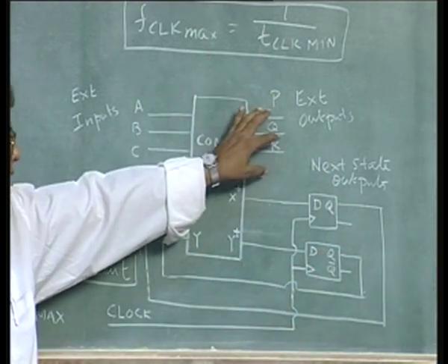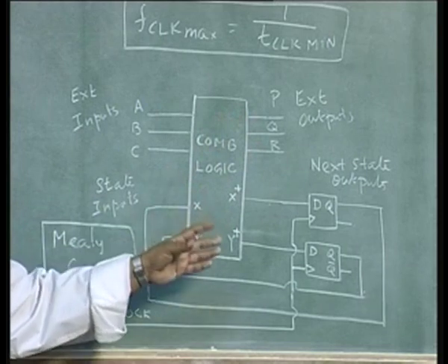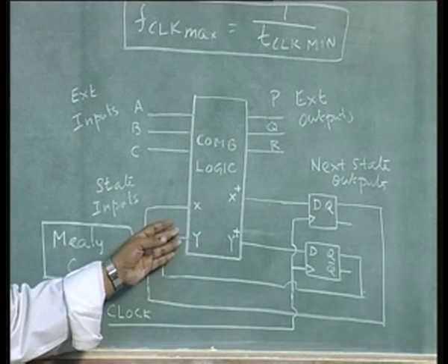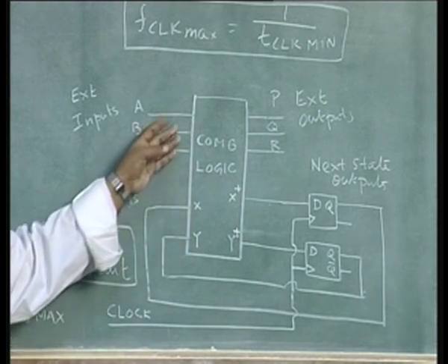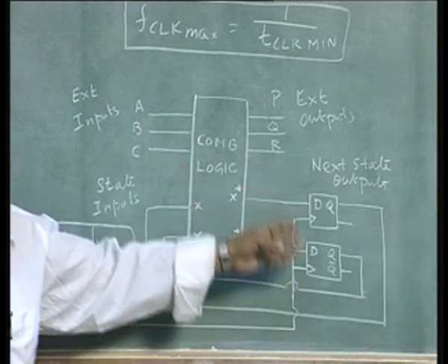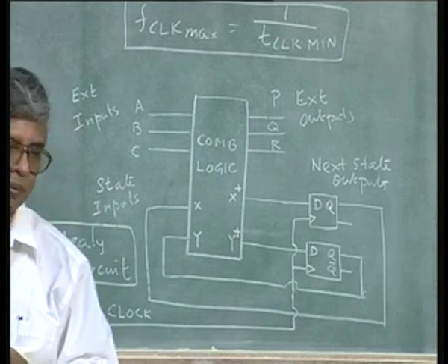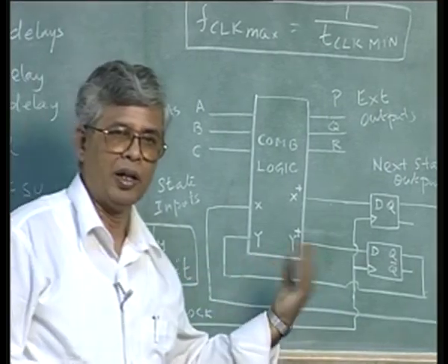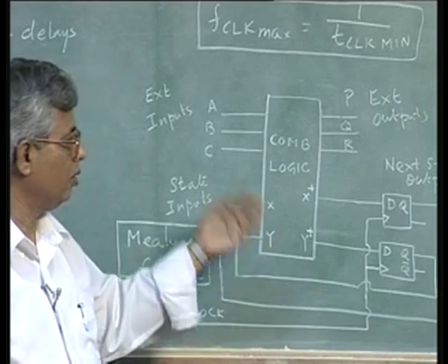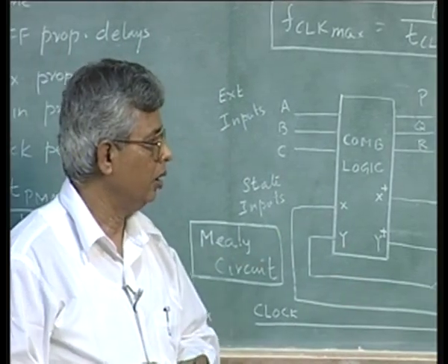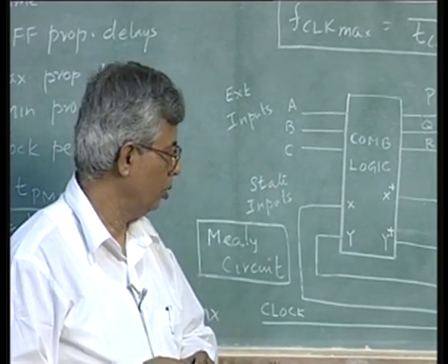What are the outputs required externally? What are the states? How many states are required? Based on that, state variables are defined, and the present state variables along with the inputs design the next state variables, etc. This is a standard procedure that gives a lot of design methodology, which we will adopt in the subsequent lectures in order to design different types of digital systems.